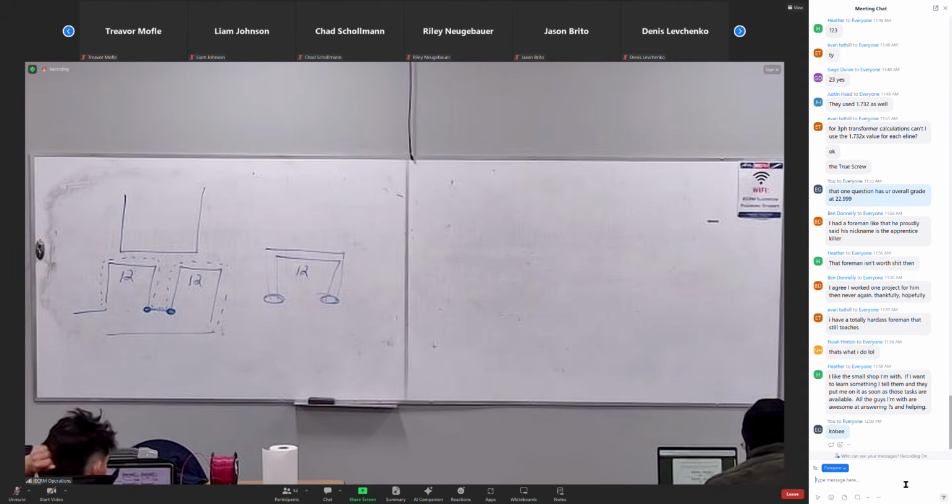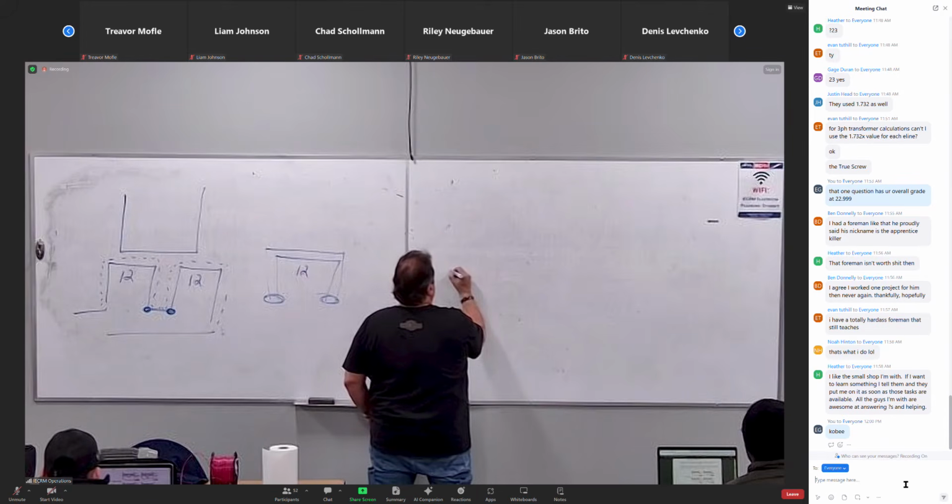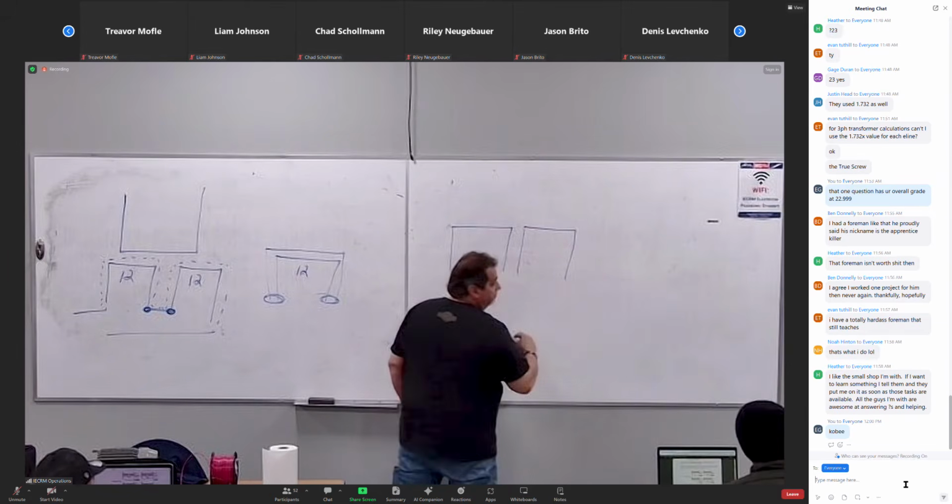No, what happened in that drawing right there is I shorted that whole transformer out. You know how I shorted it out? I took X4 and tied it to X1 and bypassed all the windings. Now, if I were to take that X1 wire and take it to the load, that would be a 120/240 volt connection. If you had your 1, your 2, and your 4 all connected to your load, would you call that a series parallel connection? Basically it's a 120/240 volt connection.